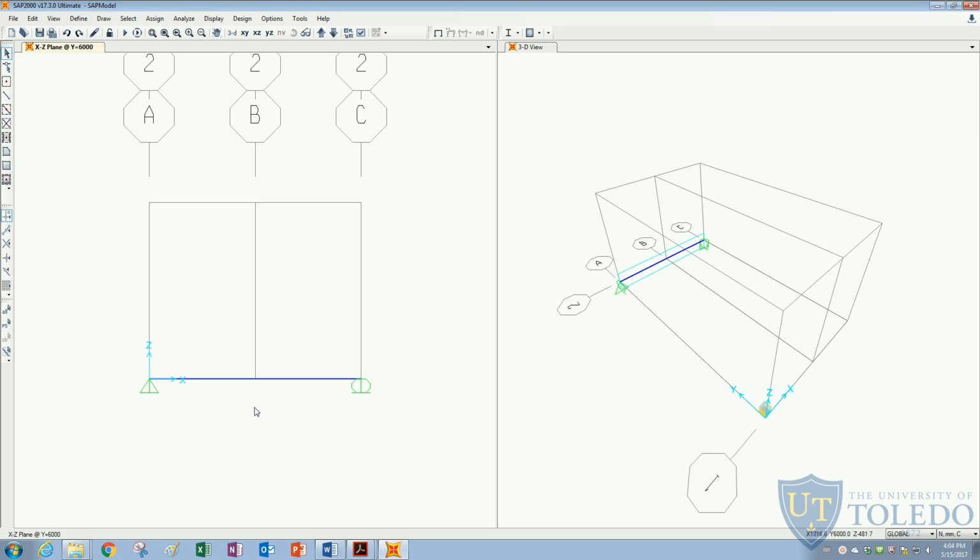The shear hinge is a little bit different than the moment hinge in terms of its placement. Shear hinges should also be placed at a critical location, but for shear there is a different concept of where the critical location is. For this problem, I will use the definition of critical location that the ACI code uses, and I'll show you right now what it is.